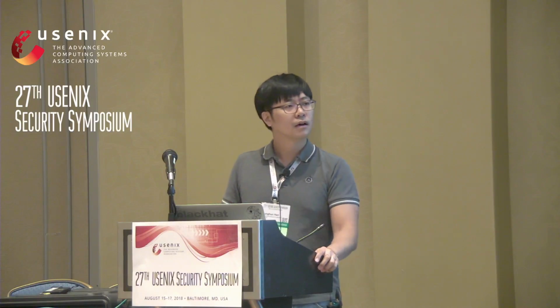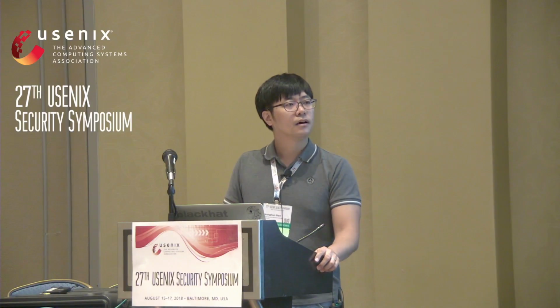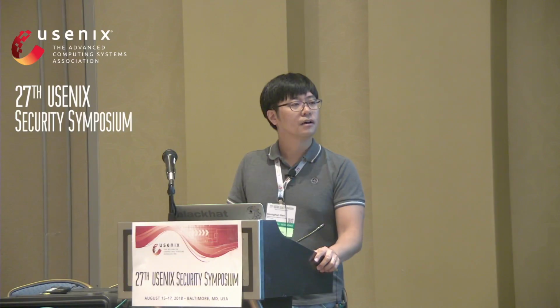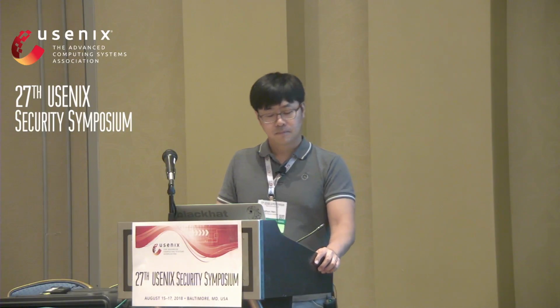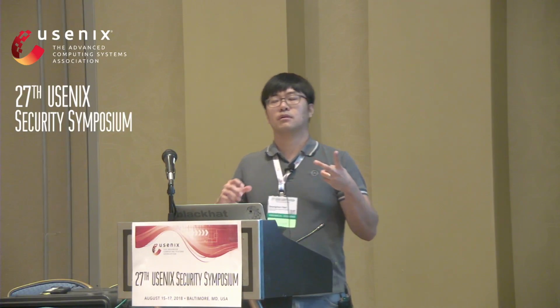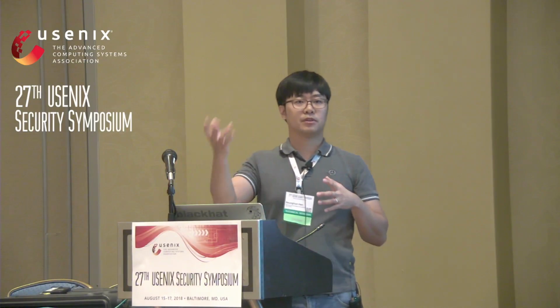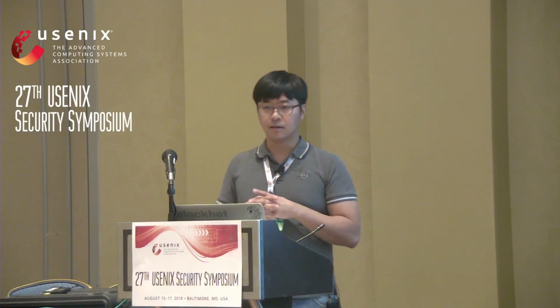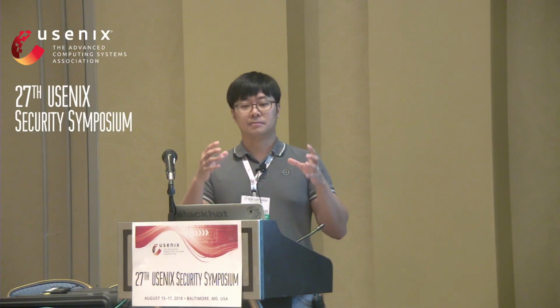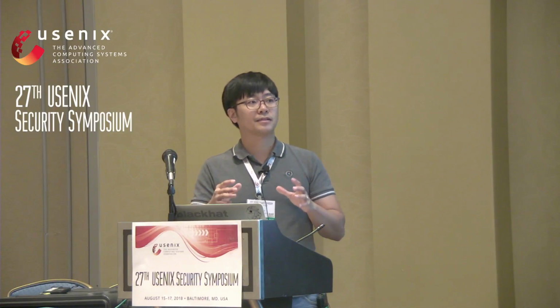I actually have one quick question too. Is it possible for these vendors to push the firmware, or is this only a change they can make in newly manufactured products for the gray area vulnerability? There are two ways to fix this gray area vulnerability. One is that the TPM manufacturer makes new firmware and updates the TPM. The other is that the mainboard manufacturer makes new firmware to handle the corrective action.